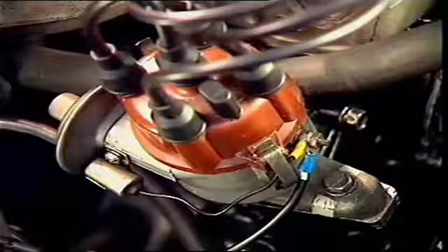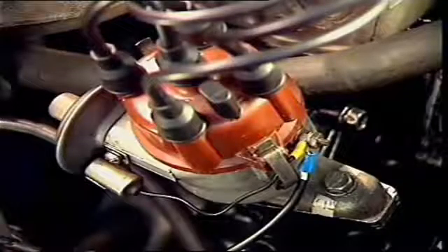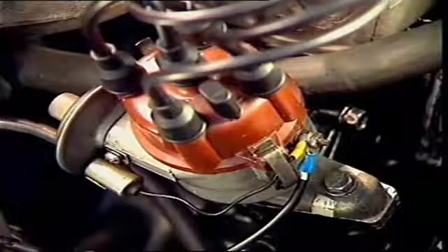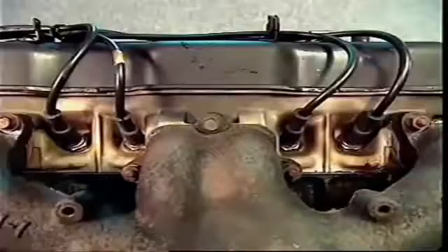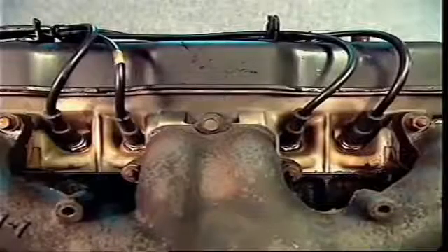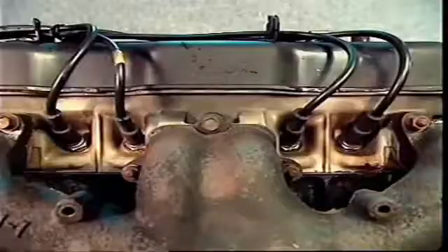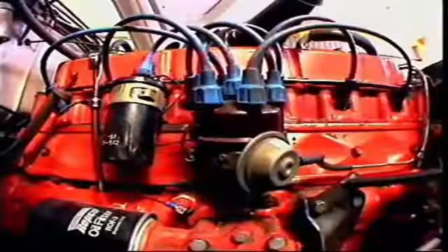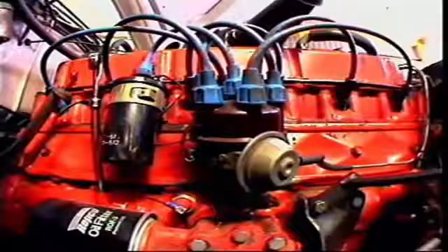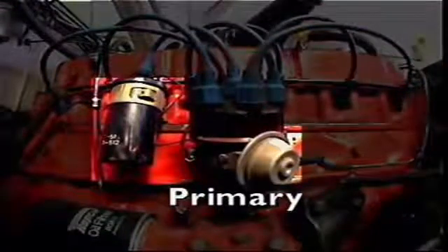and a distributor, to house the contact breaker and distribute the high tension voltage from the ignition coil to the spark plugs to ignite the air-fuel mixture in each cylinder in the correct firing order. Connecting wires and leads are suitable for conducting the current flowing in the system at the appropriate voltage level. When these components are connected together, they form two distinct circuits, primary and secondary.